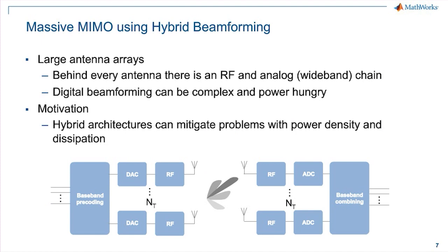Now, I told you large antenna arrays become a must for millimeter wave communication, even for the regular frequencies. Now, you can choose an all-digital beamforming approach when you are doing MIMO communication. Of course, beamforming and spatial multiplexing are two modes of using MIMO techniques, the multi-antenna techniques. In beamforming, we essentially have one stream that we repeat across different spatial antennas.